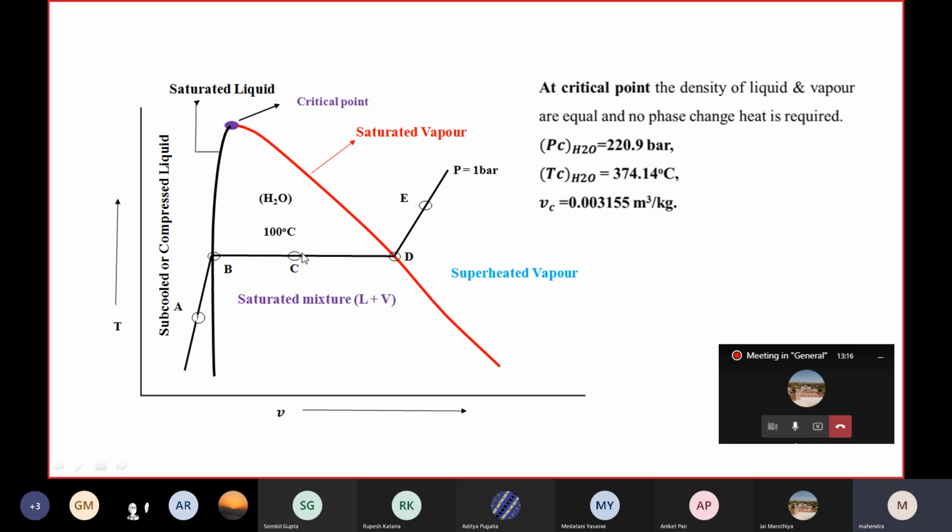And we are considering this for water. As you know very well, at atmospheric pressure the boiling temperature of water is 100 degrees centigrade. When you keep on increasing the pressure, this latent heat part is reducing. Why? Because with increasing pressure, the volume is decreasing, and the heat entrapment in this particular zone is also increasing. At one point, this is the point, latent heat is completely zero.